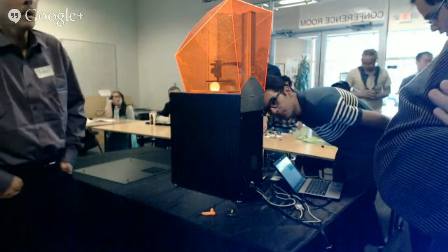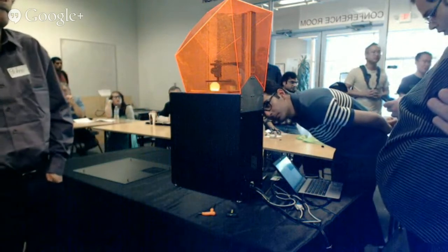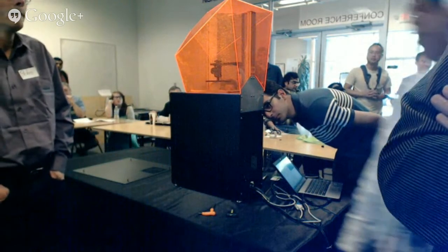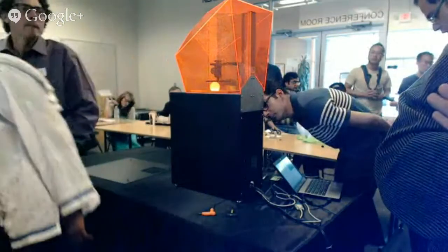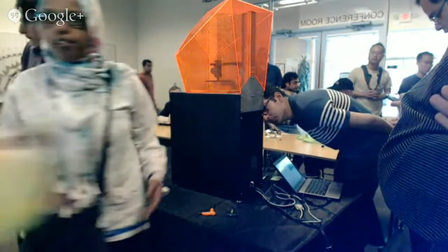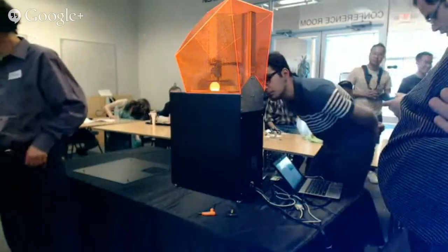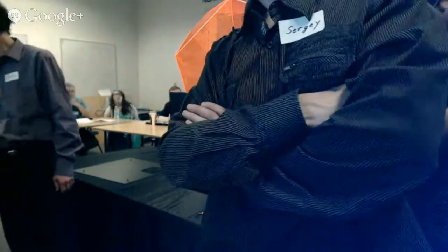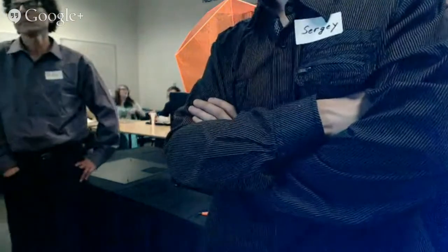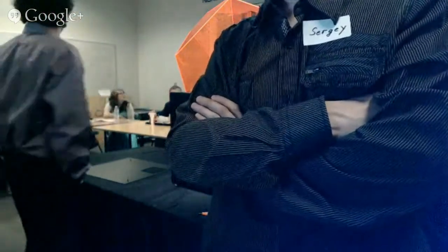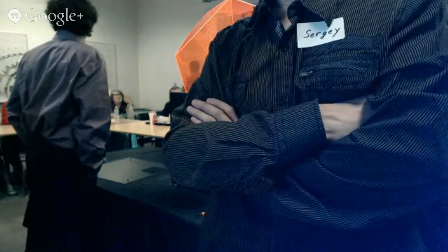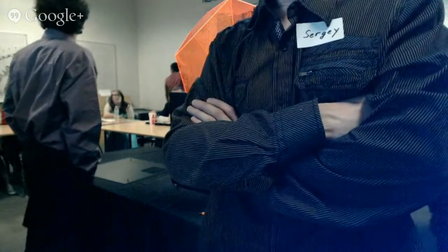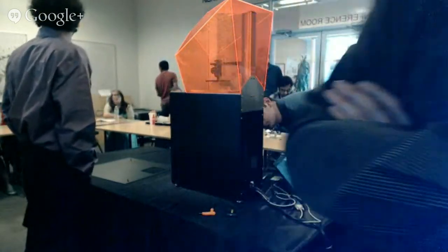Our film here is virtually indestructible. It will not be chemically harmed no matter how long I shine light into the resin, and it's in contact with reacting resin. I have a different concern, and that is my film does not release as well as silicone. So the harder I cure resin, the more strongly the resin will stick to it, and the harder I'll have to lift, or I might damage the film, right?